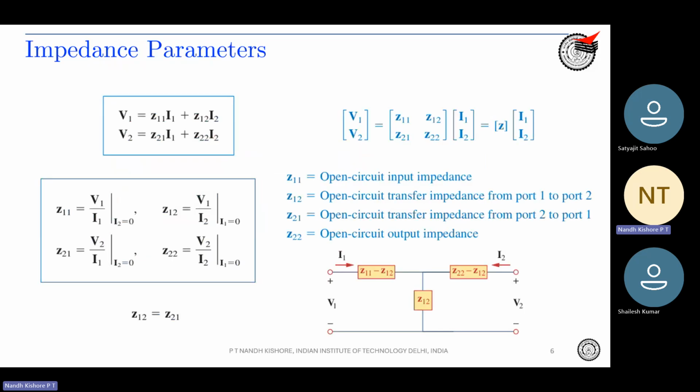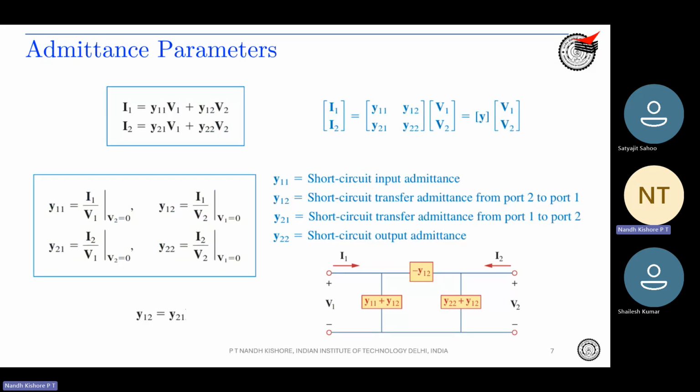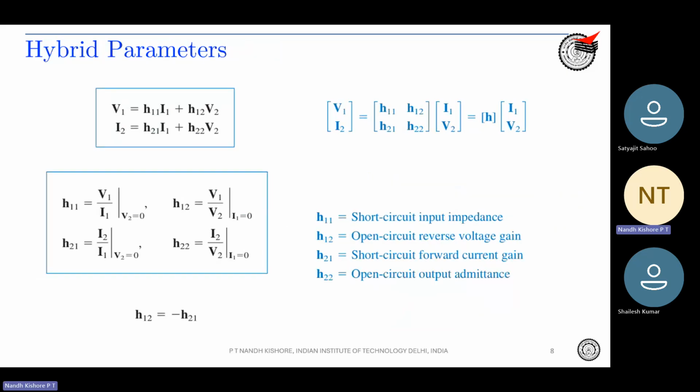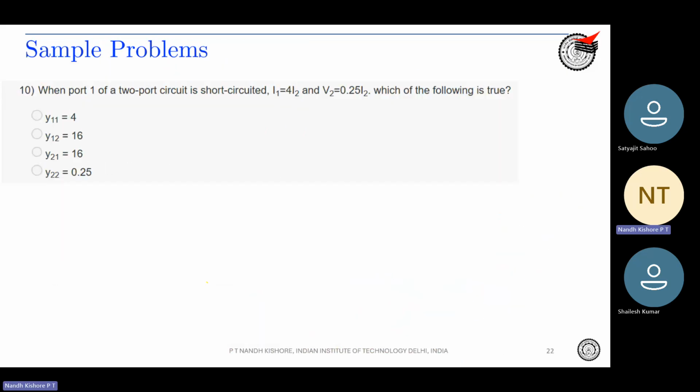Okay. So we go back to your Y parameters because the question is on Y parameters. In this particular set of equations, you just put V1 equal to 0. So the equation is going to reduce, right? We will go ahead and solve it. So what you have is [I1; I2] equal to the matrix Y11, Y12, Y21, Y22 times [V1; V2], correct?